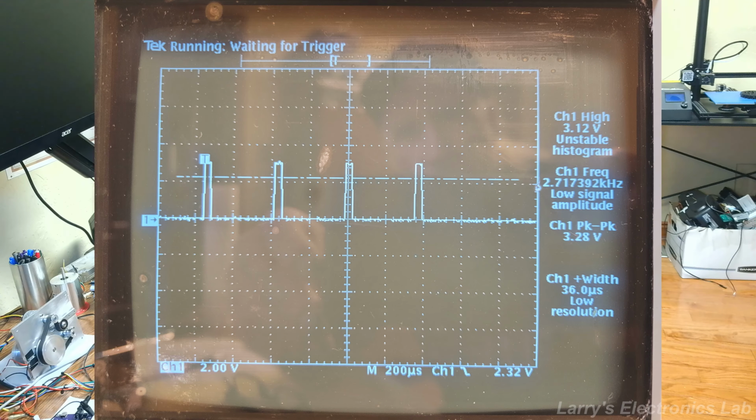you see that the tone hasn't changed, but the duty cycle changed by a factor of 10, right? So we're at a 10% duty cycle, right? That's because the tone is based on frequency. So we didn't change the frequency, so we didn't change the tone, but we did gain power savings because the time that it's on is reduced by a factor of 10. So that means the power usage of the buzzer was reduced by a factor of 10. So that could be an important aspect.